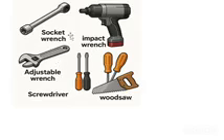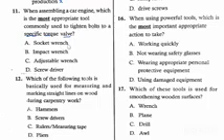So from this diagram, let us go back to our question. To start with, B, impact wrench, that one is not used. It is good for high torque, but it is not precise. Part C, adjustable wrench, that one is not ideal for torque specification. Screwdriver, used for screws and not bolts. And therefore, the ideal and the most appropriate tool is what we call a socket wrench.